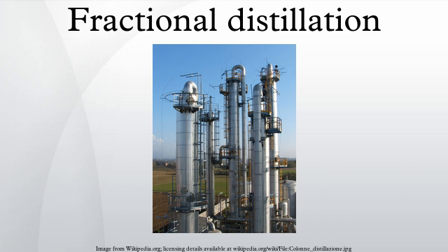Design of industrial distillation columns. Design and operation of a distillation column depends on the feed and desired products. Given a simple, binary component feed, analytical methods such as the McCabe-Thiele method or the Fenske equation can be used. For a multi-component feed, simulation models are used both for design and operation. Moreover, the efficiencies of the vapor-liquid contact devices used in distillation columns are typically lower than that of a theoretical 100% efficient equilibrium stage. Hence, a distillation column needs more plates than the number of theoretical vapor-liquid equilibrium stages.